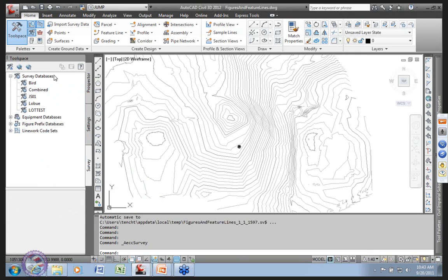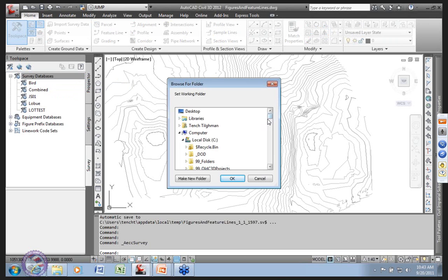Survey will use that same folder here for a folder location, or you can set it somewhere else. And since most of the time survey organizations want to bury their data away so that the design guys don't change it, we're set down to a subfolder inside our project. So survey is looking here and reading and writing text files and those sorts of things down in this location and not in the root of my project. And notice, here's the UDS compliant jump project that actually works,